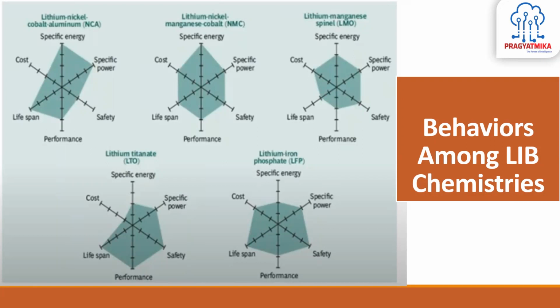the density is lower and the voltage is lower. So specifically for two-wheeler applications, and specifically for scooter applications, this becomes a little uncomfortable because the size of these LFP chemistry cells is quite bigger, whether they are cylindrical cells or prismatic cells. So the size is bigger, and there is a higher self-discharge in the LFP chemistry. So every chemistry has some good points and some bad points.